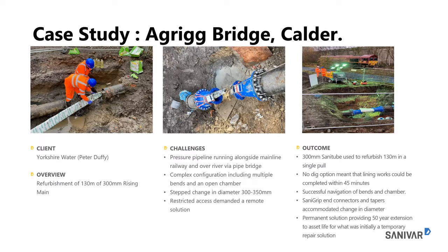In fact, it came off and down the embankment at 350. So you'll see that we use tapers at the end of the 350 mil line, being fed in on the left-hand picture in folded form into the pipe at 300 mil, but exiting the pipe down the embankment at 350 and then being taken back to tapered at 300.